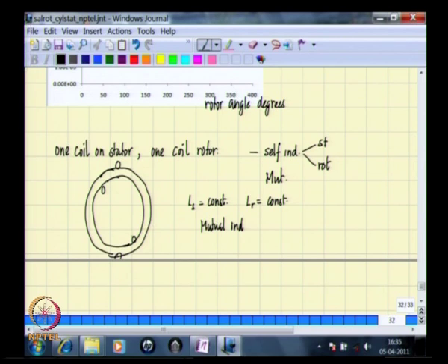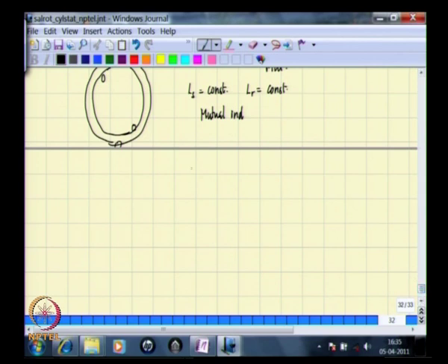We took the actual flux density variation, which would be a square wave in this manner, and then as the rotor coil moves, the rotor coil is initially positioned here, and as the rotor coil moves to some other location, say here and here, as the rotor rotates, it is equivalent to this coil moving on the x axis. As this moves, we then try to find out the net flux by taking this area of flux density. We try to find out the flux linkage.